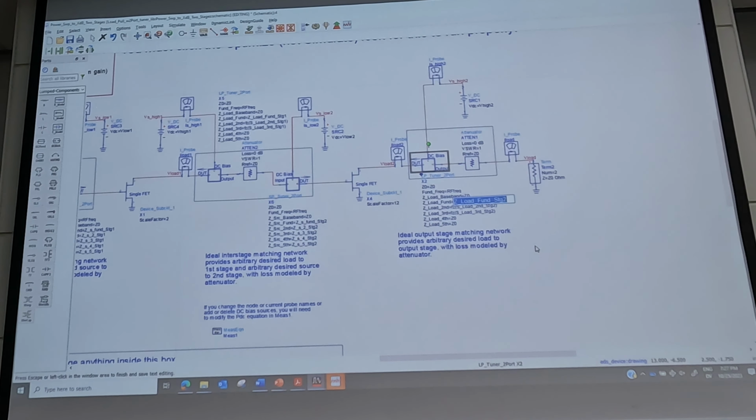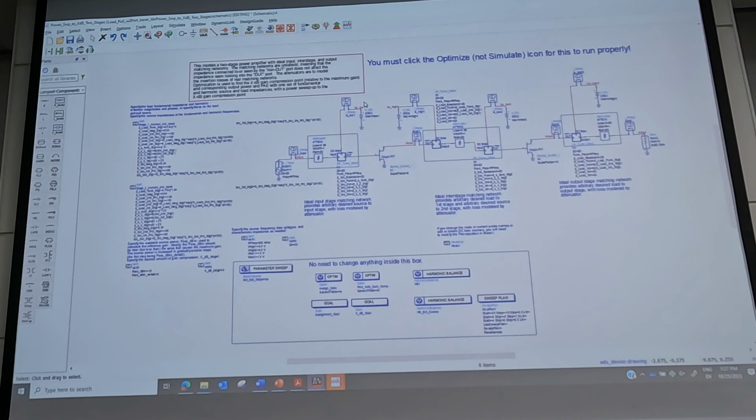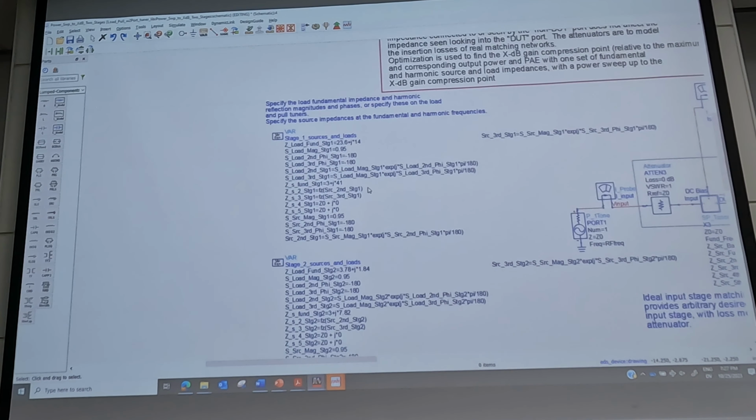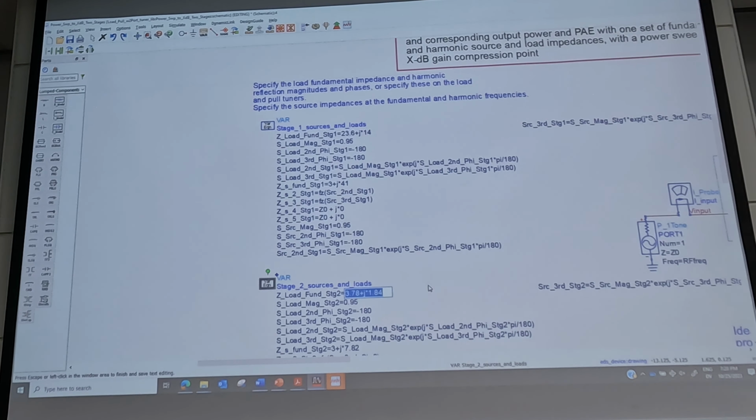It's just the result. I looked at the data display and said, okay, this is the best value, and I'm putting that in. That's here. I got this value from the first stage load pull, and I got this value from the second stage load pull. I just entered it. So it's not doing another load pull here. It's just holding it constant.